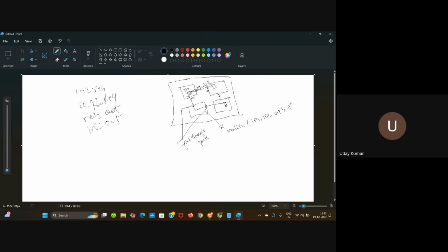Initially, in physical design, you have seen an issue here: you want to propagate this particular signal through this block. So what you will do is create dummy ports. Let us say these are feed through ports, FE1 and FE2. FE1 will be an input port, FE2 will be an output port.